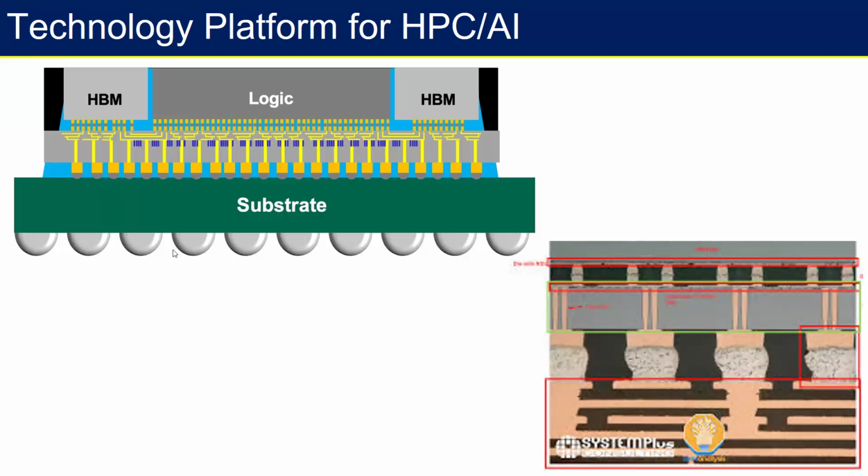That is nothing. Basically he is putting this array or the solder attach, which is a material, obviously, which we know in the industry as something called SAC alloy, right? So SAC means tin, silver, copper. These are the three materials by which you make this material, which is SAC, and then you attach that to the substrate. Now the question is, what is a substrate? If you have seen a board, typically the boards in PCBs, this board is a laminate board, right? So it's a plastic board, which is what we knew earlier as the printed circuit board. But here the laminate is a substrate. So it's an organic substrate.